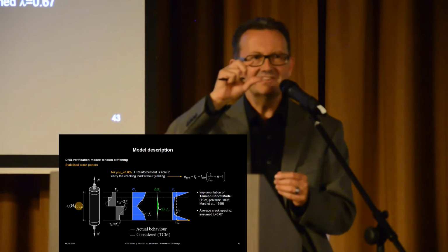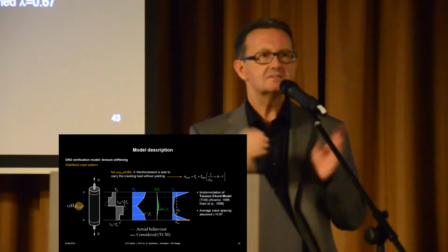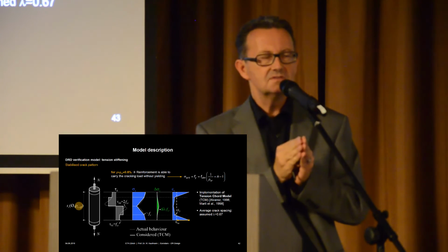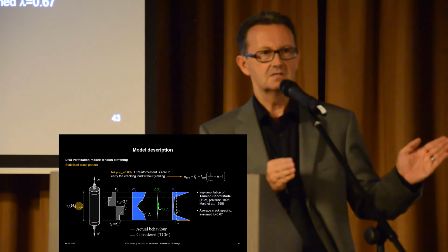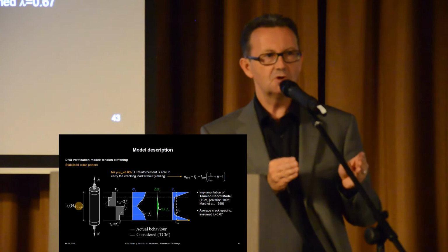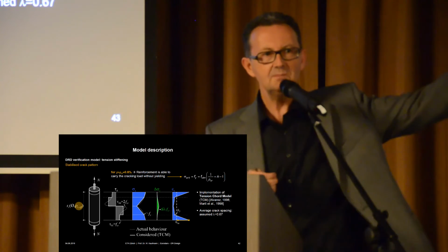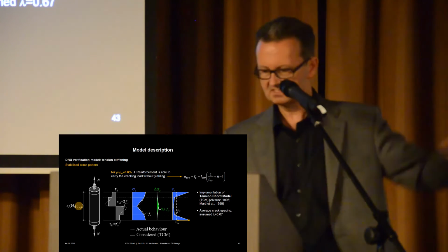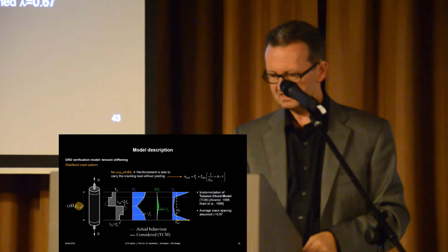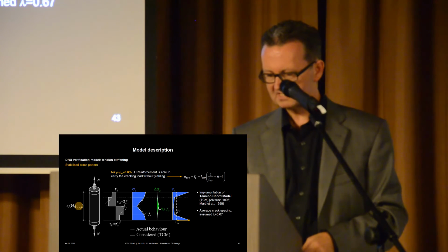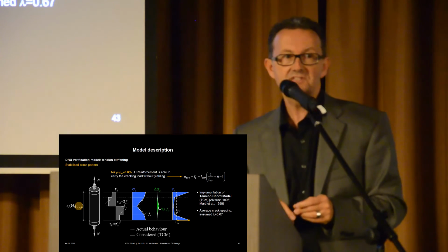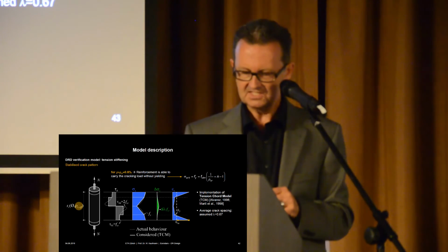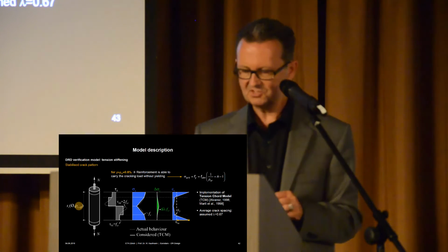It's so little contraction at that moment, but the strains at the moment and the slip with that, the steel strength and the slip increase dramatically once the rebar yields. So we have tenths of a millimeter before it yields, and you go into millimeters and more once the rebar yields. So this curve actually doesn't look like this, but it looks like this transition area virtually doesn't exist. Then it's not so important to really capture that exactly.